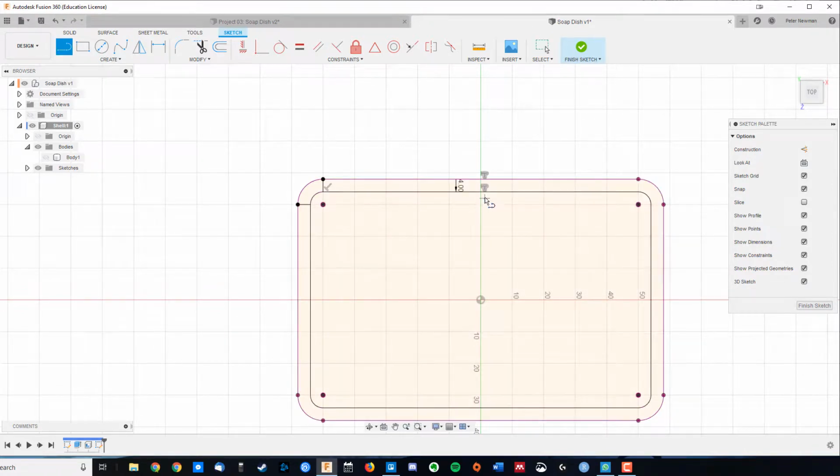So the first thing you need to do is actually put in a line. Put in some construction lines here, and I can just go from the center out to there. Remember, X is for construction. And now I can go mirror, and the things I want to select are these. So 2 objects, mirror line, this one here. You can see they appear over in this corner. Perfect. Go OK. And now I want to mirror again, and I can mirror around this line here to bring both of those down there.